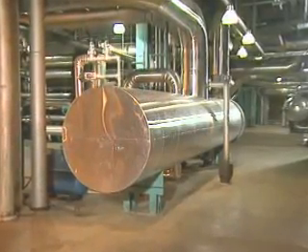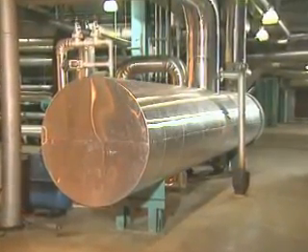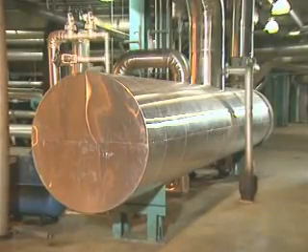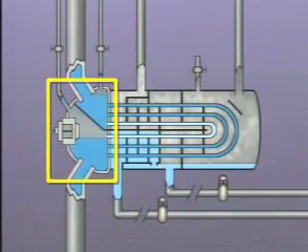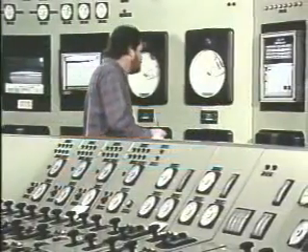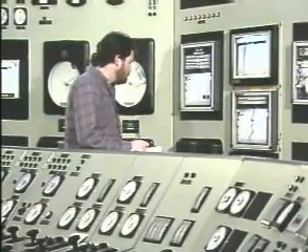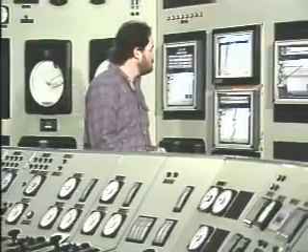Improper venting of a heater can cause air binding. When this occurs, air is trapped in either the tube side or the shell side of the heater. Air that collects in the water boxes on the tube side of the heater can restrict the flow of water through some of the tubes. The restricted flow causes the velocity of the feed water to increase because the same amount of water must go through fewer tubes. The increased feed water velocity can cause the terminal temperature difference, or TTD, to increase, although the drain cooler approach, or DCA, remains normal.